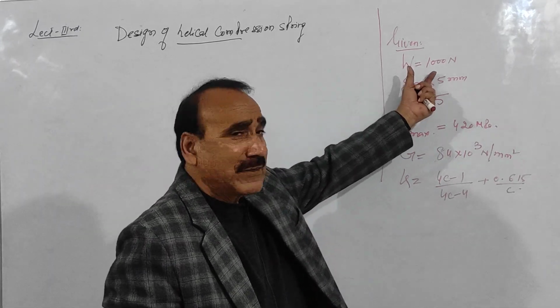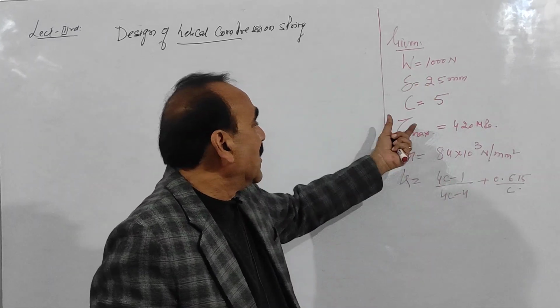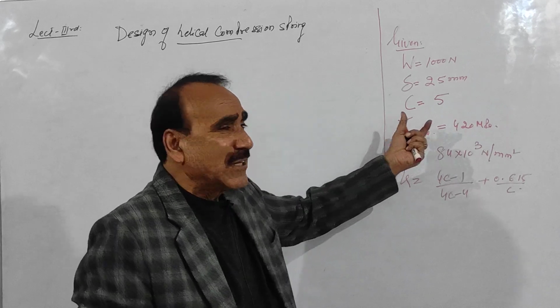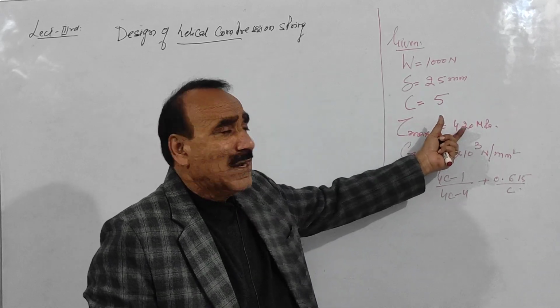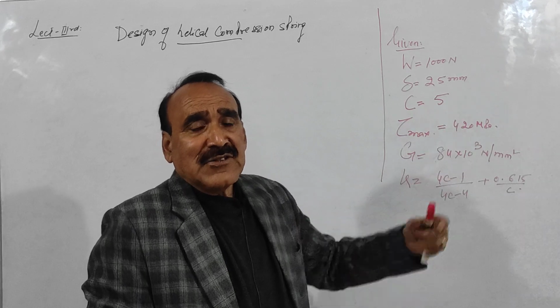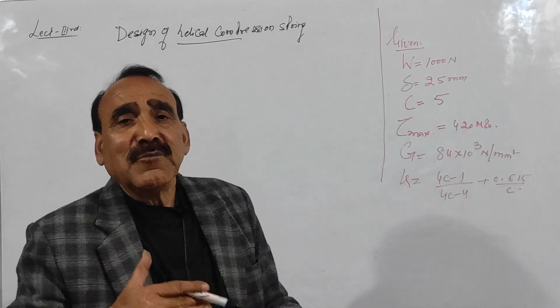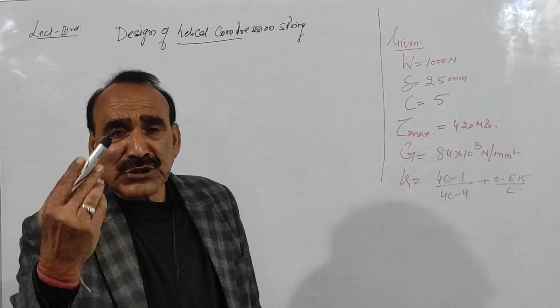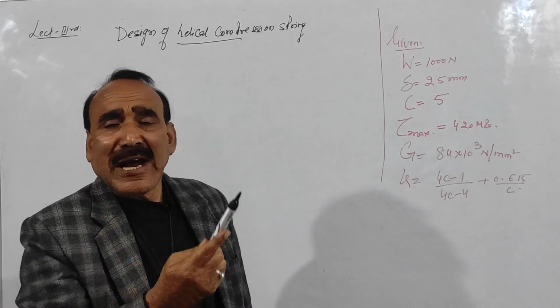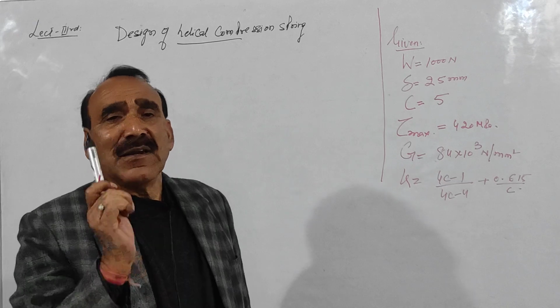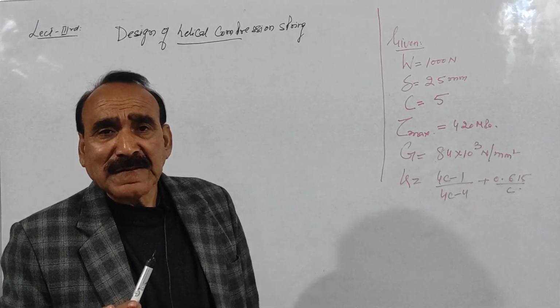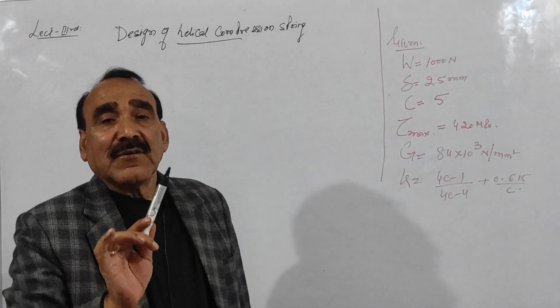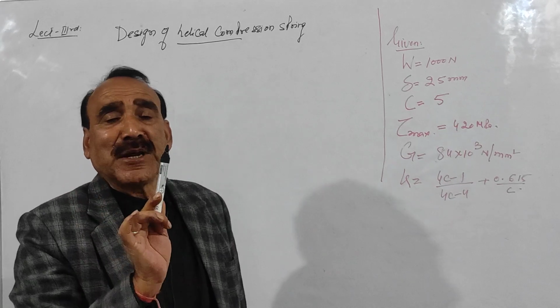ये जो एक्शन लोड कितना है 1000 न्यूटन है. मैक्सिमम शियर स्ट्रेस कितना है 420 MPa. तो इसके ऊपर हमें, क्योंकि जो स्प्रिंग है वो किसका बना है, that is made of wire, उसी को हमने कॉइल इन शेप ऑफ कॉइल we have given. तो फर्स्ट we will find out the diameter of the wire, देन उसको एक कॉइल की शेप में हमने स्प्रिंग देना है.